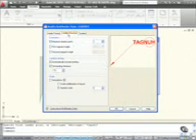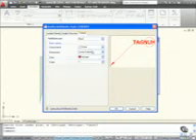Now if I go to the leader structure here, maximum leader points I've got 2. First point there, at the end of the arrowhead. Second point is at the crank there. Automatically include a landing, so that's that little horizontal line there behind the word tag. And the landing distance is 7.5 millimeters in this case. Now, content. This is where it gets interesting.